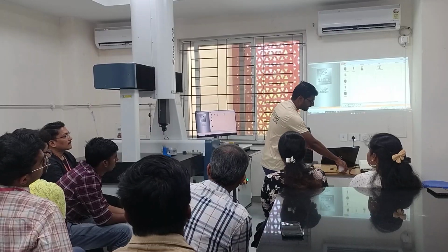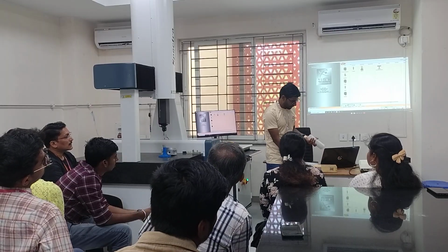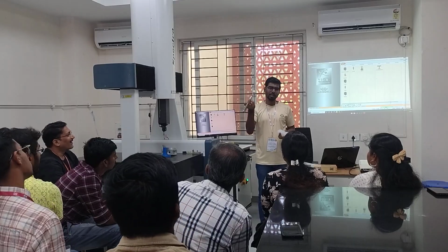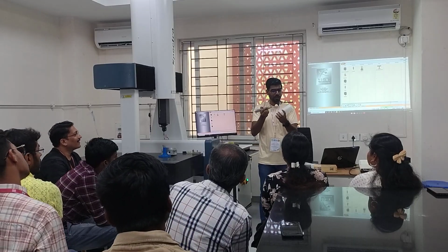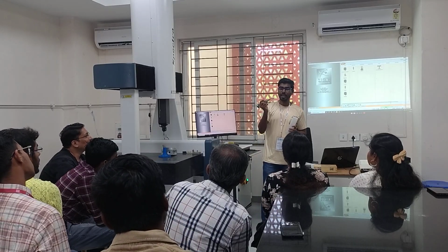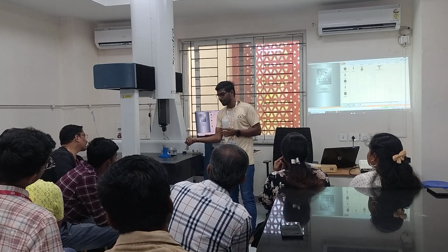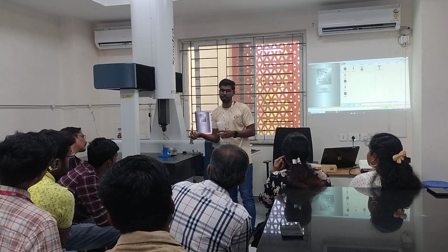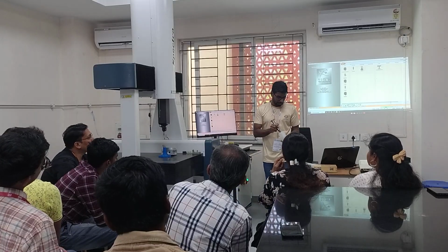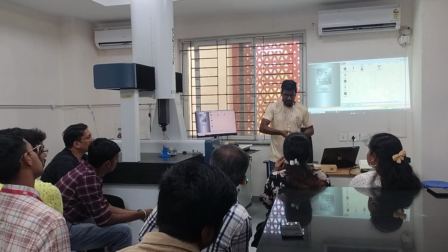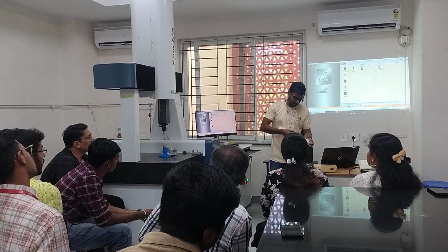This reference is given by the company and it has a 29.9983 diameter. So we have to calibrate it and tell the machine, okay, I am calibrating and this is what your measurement should be. That is what is required when you are doing any kind of measurement. Calibration is not required often; every 1 year they prefer to do the calibration.